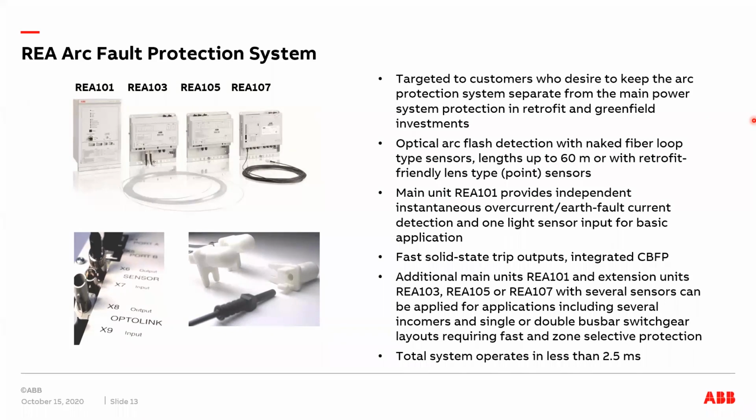Additionally, we secure and we recommend always to secure the optical arc fault detection with simultaneous overcurrent, and REA 101 unit has instantaneous independent overcurrent or ground fault current detection.